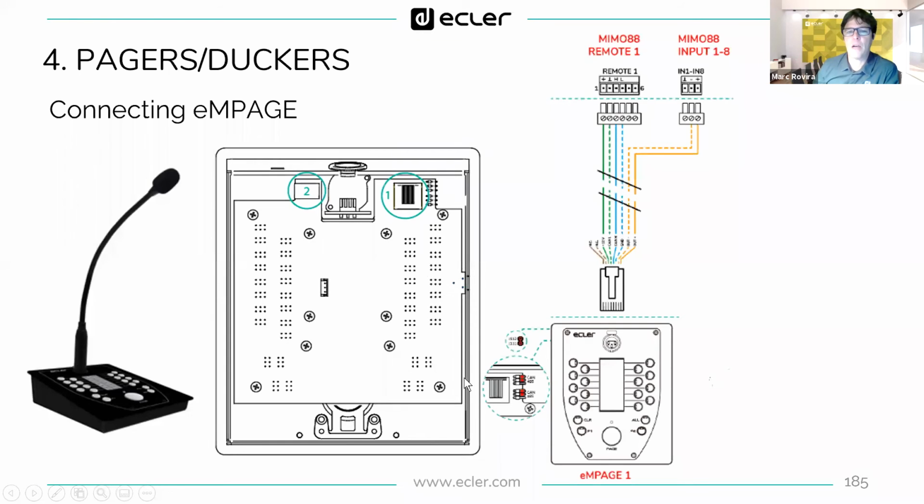So how do we connect this? The RJ45, there are several, as you know, colors. These are the standard colors, or if not, you have to count the pins. And you have to connect the audio signal onto the corresponding input and the control signal to the remote port. Here the remote, we have plus and ground, which is the power supply for the unit, and H and L is directly the port.